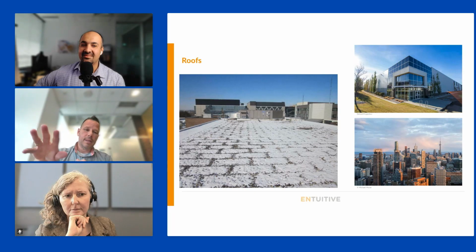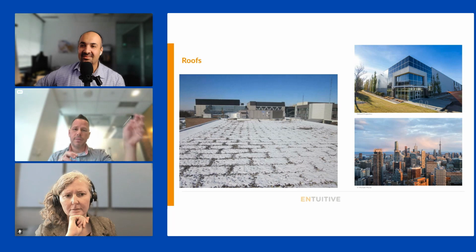And then the other thing that's happening in the background here is you have a bunch of intersecting interfaces. So that thermal bridging idea from earlier in the presentation absolutely applies to roofs. And so you're going to have a slightly derated roof because you have things like penthouses and parapets, and it depends whether you assign the parapet to the wall or to the roof. So that's a decision that has to be made in design. But again, just a good example to show that the design of the insulation also matters.